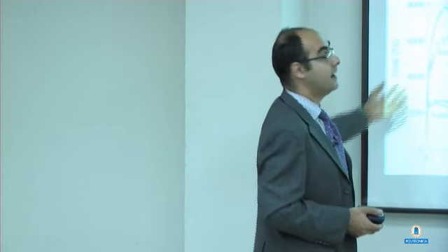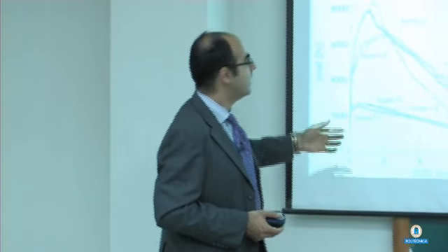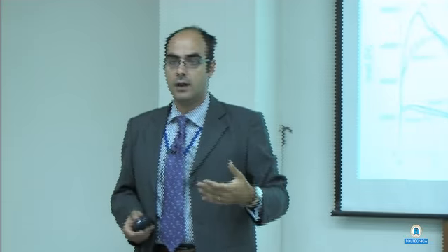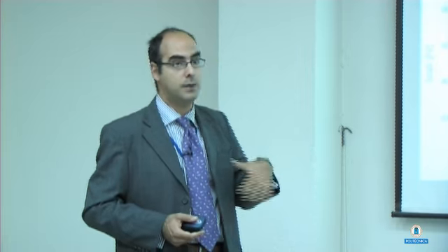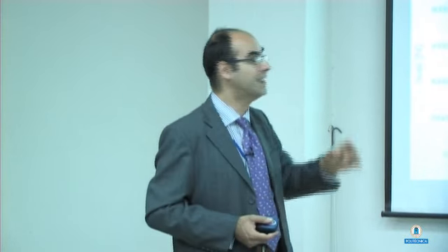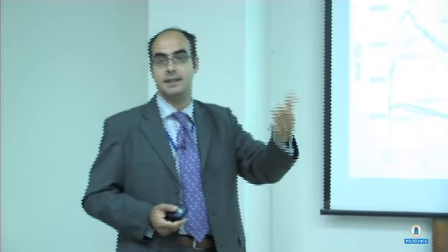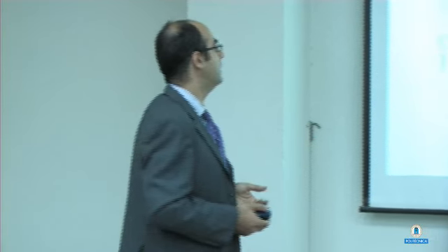So basically the fibers were effectively oriented. This remarkable difference could not be justified otherwise. And there is still some effect of downward settlement, which we are working on to improve the mix design to better check also that, because we want to go further with some other kind of elements, for example curved elements or ribbed elements, and in that case the downward segregation is much more important than in this case of very thin elements. Most of all, if they work in the same direction as you cast, the downward settlement could not be a problem, could be only beneficial.